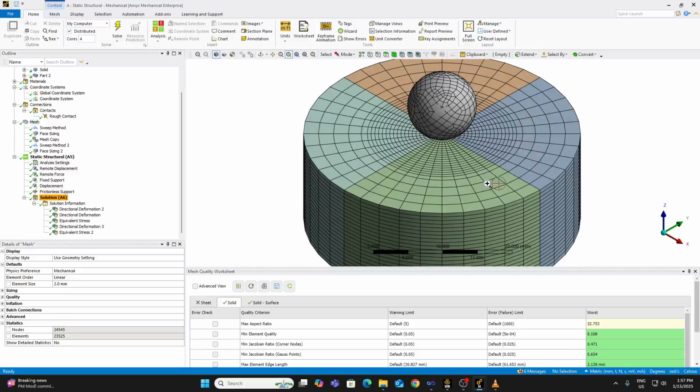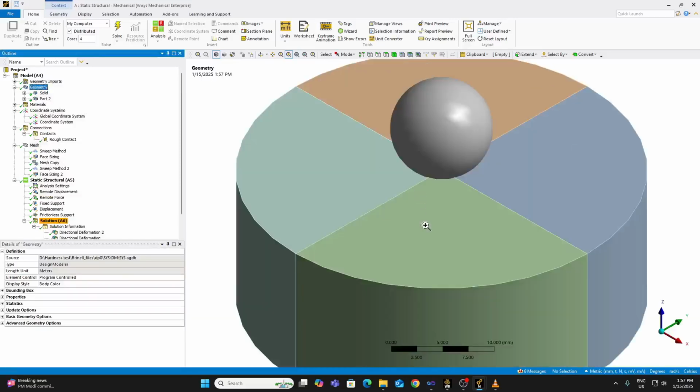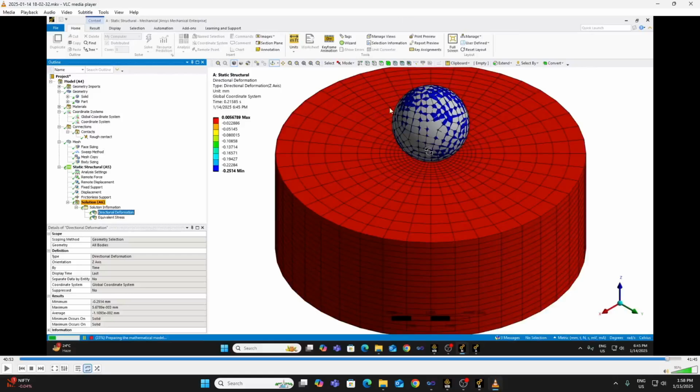In that previous example, while it was being copied from the body on the opposite side, somehow the mesh got flipped, from the upside to the downside and vice versa, and therefore the mesh looks very different. There is a mismatch of meshing here. I was also checking, and the solutions were inconsistent, and therefore I made some corrections.